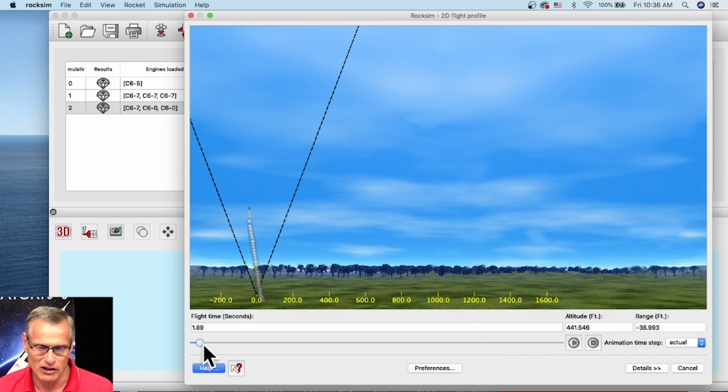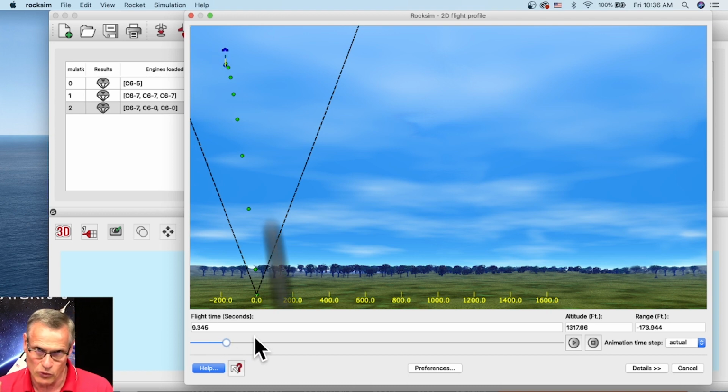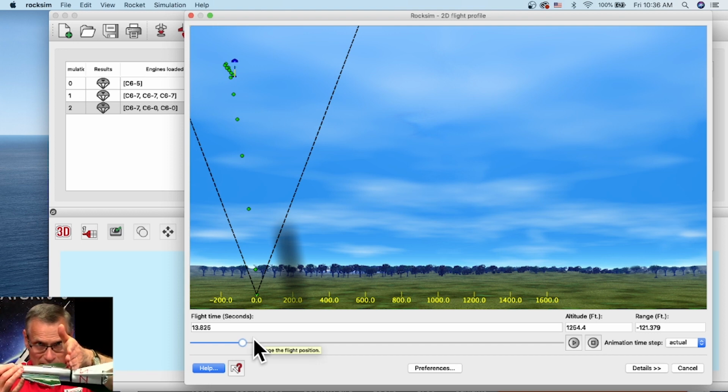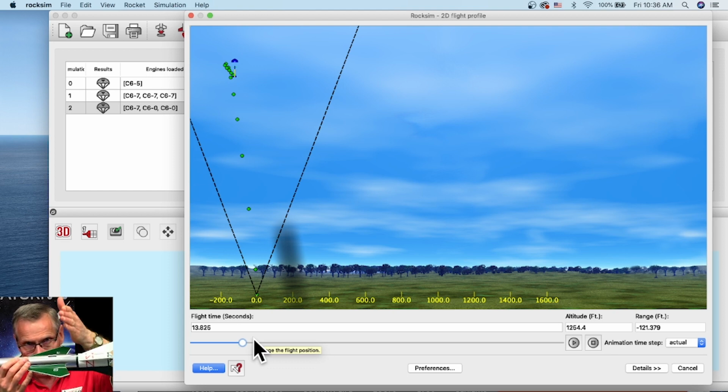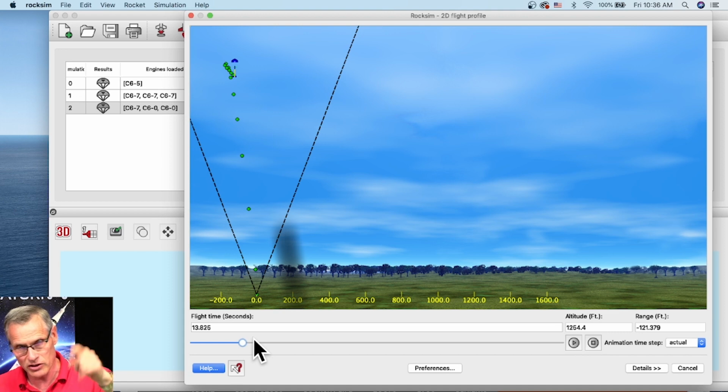So as the rocket takes off, you can see it's kind of arcing into the wind a little bit. And what's actually happening is it's arcing more into the wind than if the pods had stayed on. With the pods on the rocket, our center of gravity has moved way back, so now it's closer to the center of pressure. Because of that, the rocket is less stable, and because it's less stable, it's not going to weathercock as much. So that is the reason why it didn't go as high.